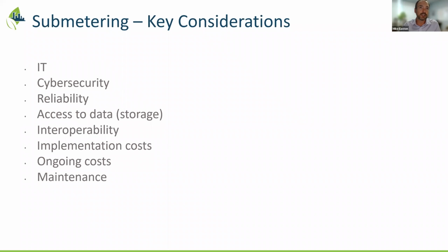One other consideration that needs to be factored in is just ensuring that all stakeholders are communicating what parameters or measurements they want out of the meters. So if you're installing a meter that's only going to give kilowatt hour consumption or natural gas consumption, but one of the other stakeholders wants instantaneous data, they want pressures, they want kilowatt demand, they want power factor or harmonics, that needs to be communicated early on. And often that isn't. And again, it can result in a costly swap out of the hardware if the specifications are not meeting what the end operator wants. So those are our cautions.